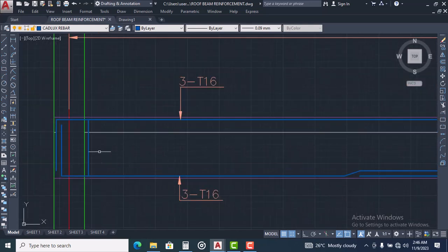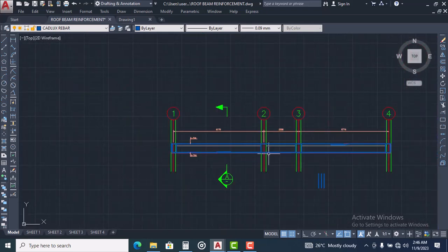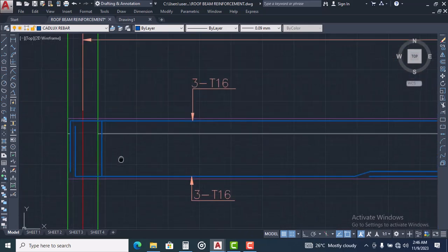So this is just a way to strengthen. Some use 300 too, you understand? Then 300, 200, 250 for the beam stirrup. I'll use 300 here since it's a simple beam. So I'll use 300 for the spacing.